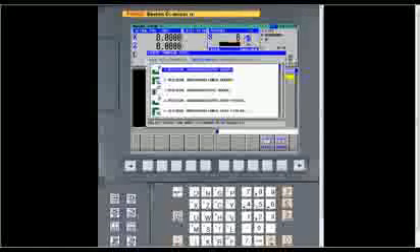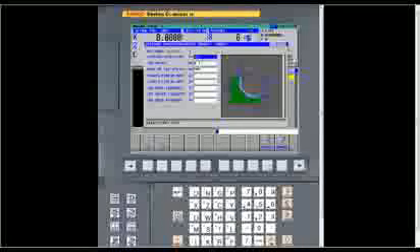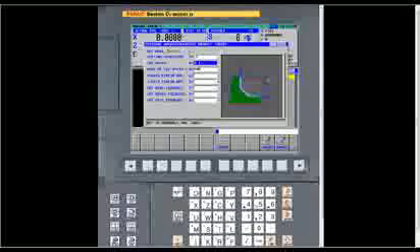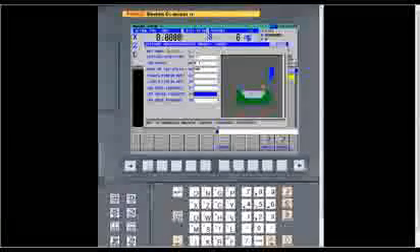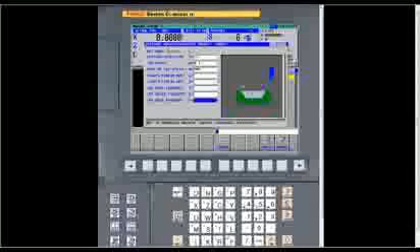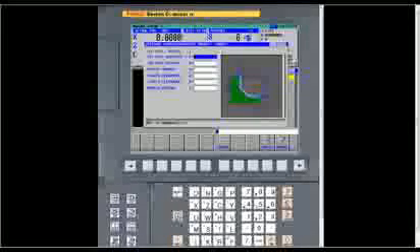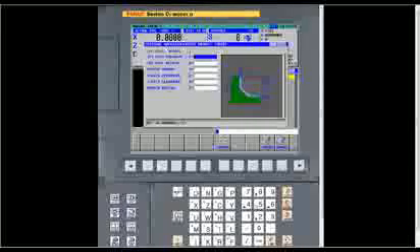The next tab is residual machining. And just to give you an explanation of what that is, say for instance we're turning a part that has a large relief that only one particular type of tool will fit into. What the software does, as long as you have your tools described right, it'll look and see if a tool has clearance to get into that relief. If it doesn't, it'll give you a little message saying residual stock will remain. That tells you that you have to go into this cycle and select that and fill in the blanks just like before. Again, it's got Z minus, Z plus, and it looks just like a rough turning cycle, exactly the same fields. And the software will actually then take the tool that will fit into that profile, and go in and just take out the stock that's left. So that's residual machining. Again, as I said, it looks exactly like the other cycles. Just fill in the blanks.